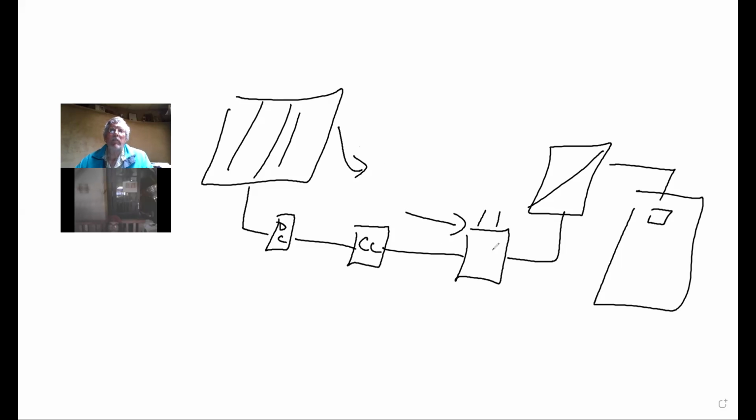If the battery bank is, let's say, 48 volts DC, the charge controller has to be compatible with that. It's got to be 48 volts DC. Now, in the old days, the array would have had to be configured to 48 volts as well, because coming from the array to the charge controller to the battery bank, the inverter would have to be 48 volts input DC as well.